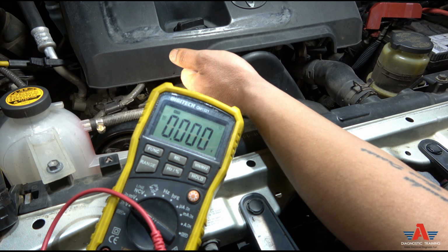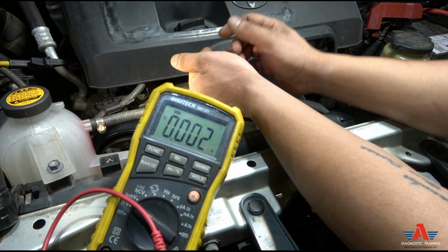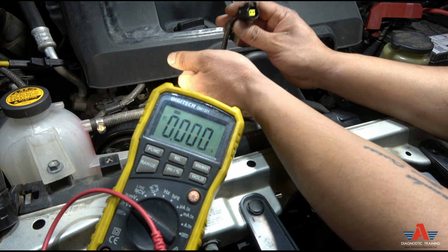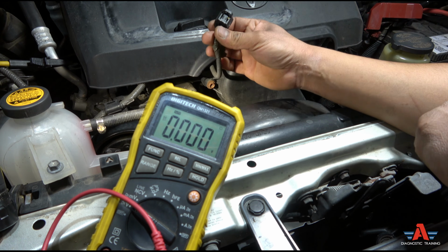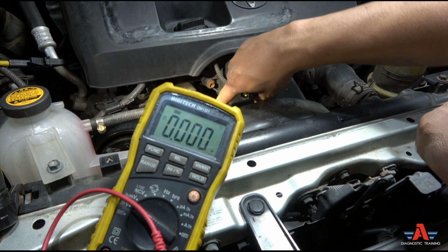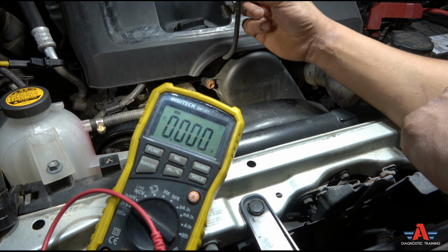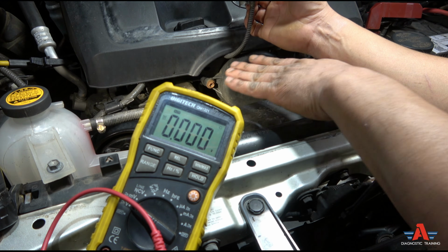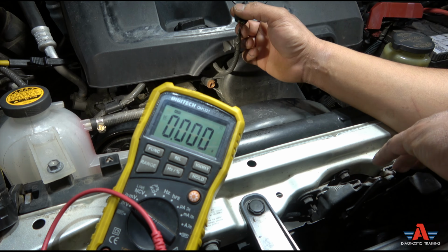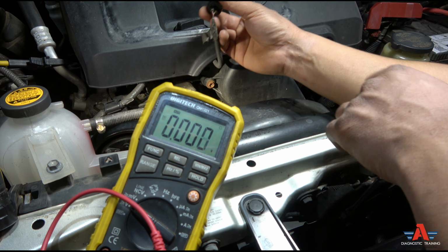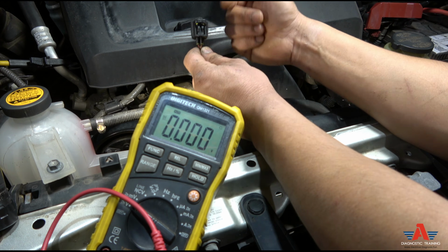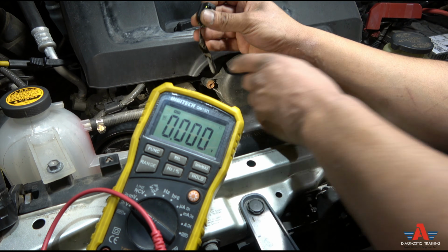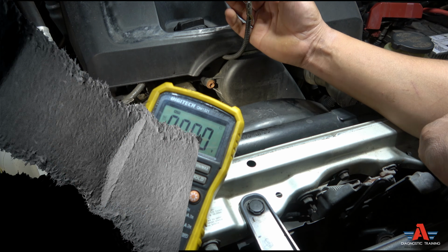Now if you got a fault code like that, voltage input high, that usually means it's an open circuit, right? What does that tell you now after those 2 tests we did? More than likely the problem is the sensor, guys. Nothing wrong with the wiring, nothing wrong with the computer. Your test is done. Put a coolant temperature sensor. That's it. Finish. Now, if you didn't see a 5 volt or the earth, now you're going to have to chase the wiring up towards the computer. You're going to need a wiring diagram or service information.